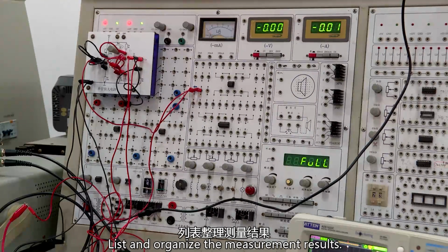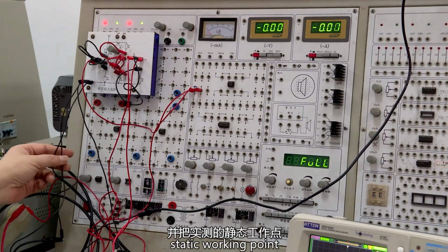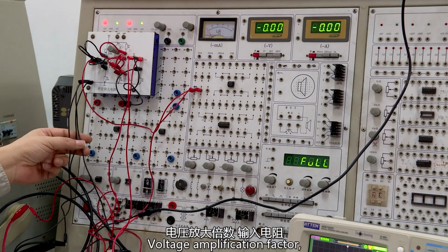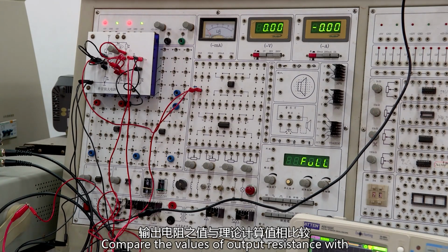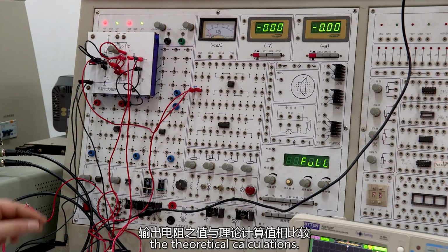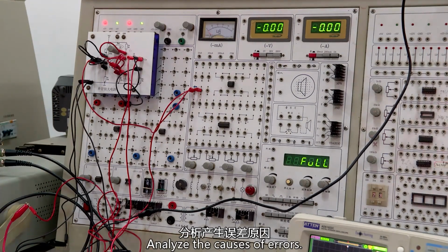List and organize the measurement results and the actual measured static working point, voltage amplification factor, input resistance, and output resistance. Compare the values with the theoretical calculations. Take a set of data for comparison. Analyze the causes of errors.